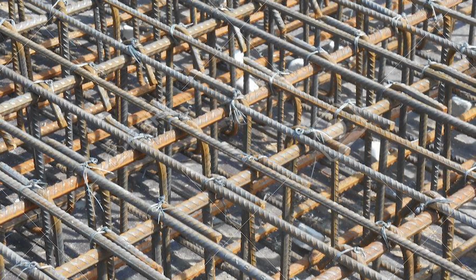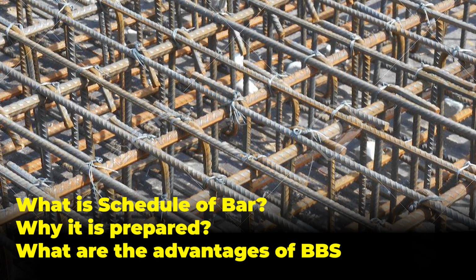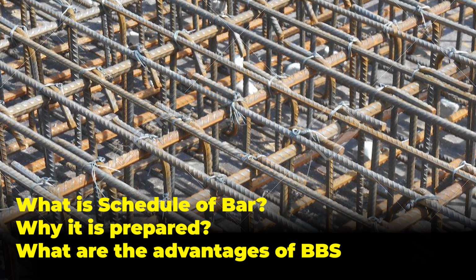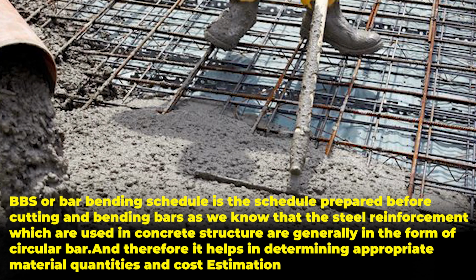Before moving into the software, let us understand what is schedule of bar and why it is prepared and what are the advantages of preparing BBS. So BBS, or the bar bending schedule, is the schedule prepared before cutting and bending bars. As we know, the steel reinforcement used in concrete structures is generally in the form of circular bars, and therefore it helps in determining the appropriate material quantities and cost estimation.